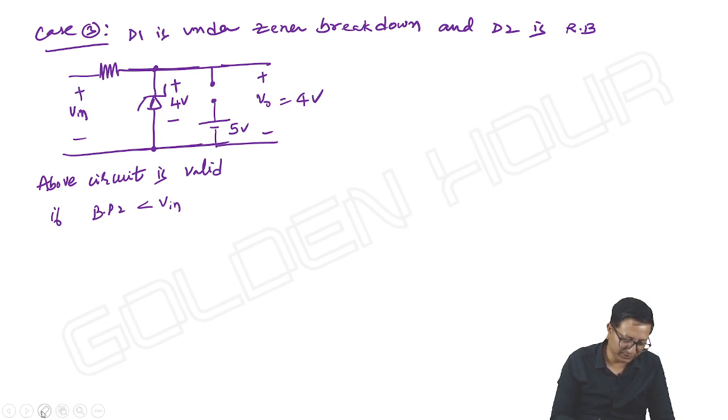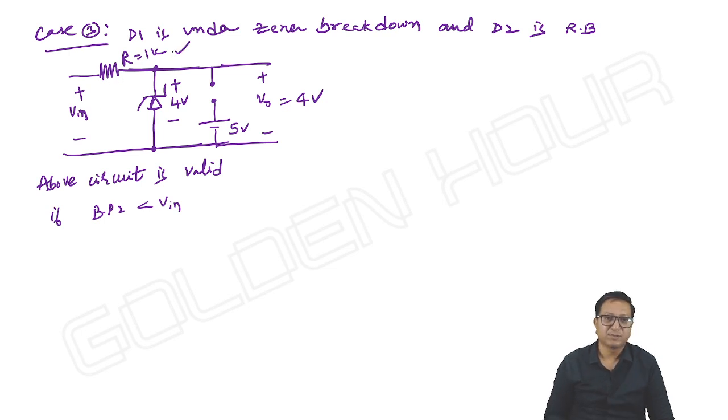The voltage across resistor will increase. That's it. Here we have 1 kilo ohm. No? So input 6 volts means the remaining 2 volts will be across this 1k. 7 volts, then voltage across 1k will be 3 volts. Like that.